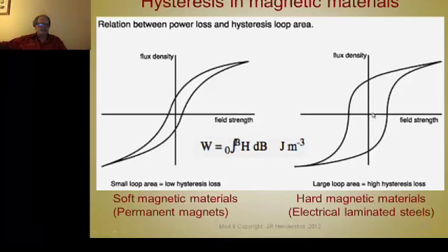If I have a permanent magnet and I start with a field string, ampere turns, big coil, the flux would rise, and then I would turn the power supply off, and the flux would decay, it would come back, and so the stored magnetic flux density in that magnet stays at this value here.